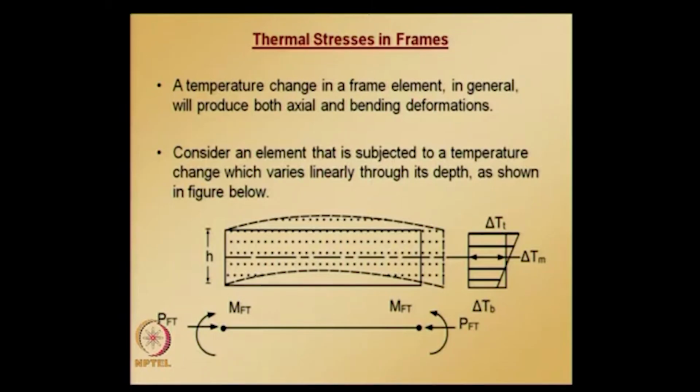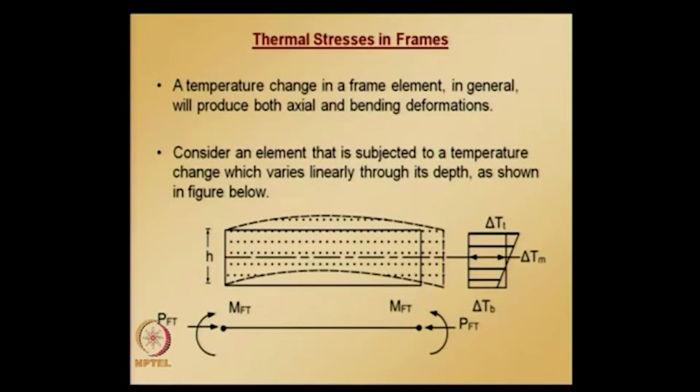Because of these temperature changes of the top and bottom surfaces, we expect the element to experience some curvature. Because of curvature, moment will be developed, and in addition, if the ends of the frame element are constrained for any movement, that is, totally fixed, fixed end moments will be developed in the direction shown in the figure. In addition, in a frame element axial forces will be developed at the ends, because if both ends are constrained, reactions will be there, and the direction in which these axial forces act is also shown in the figure. Please note that the deformation shown in the figure is for the condition that the top surface temperature is higher than the bottom surface temperature.